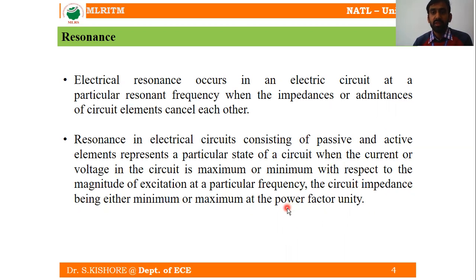If you go for the phasor diagram of an electrical circuit, when the power factor is unity, it means the angle between the voltage and the current is equal to 0. When the circuit impedance is minimum at that point, that is going to have unity power factor, right?